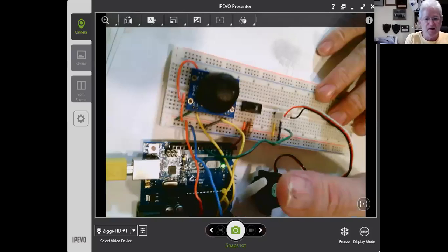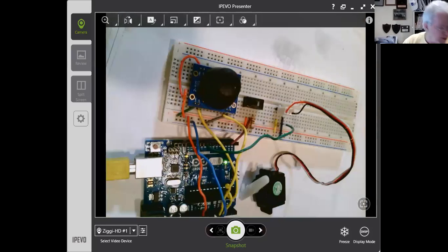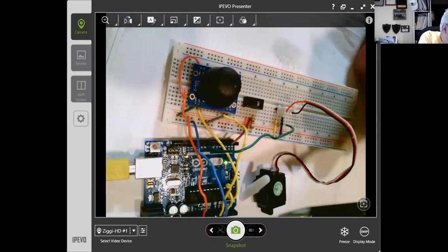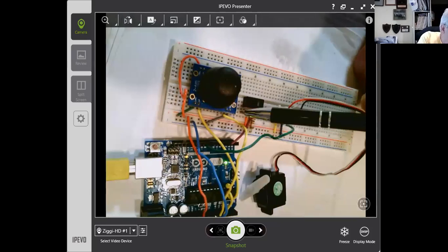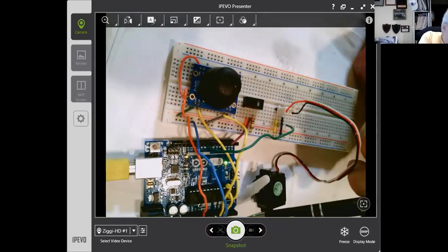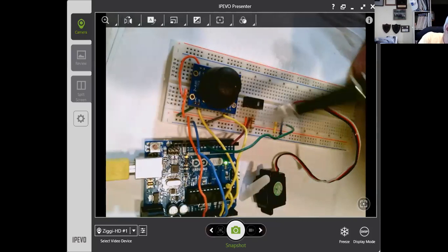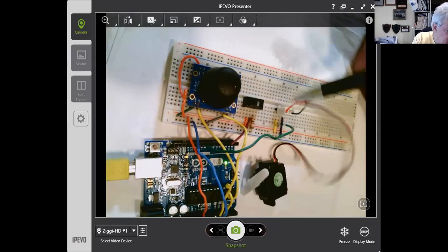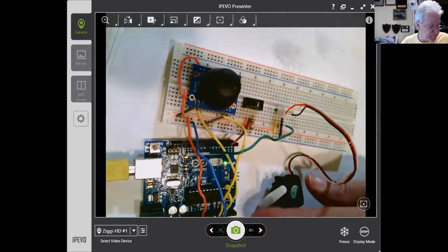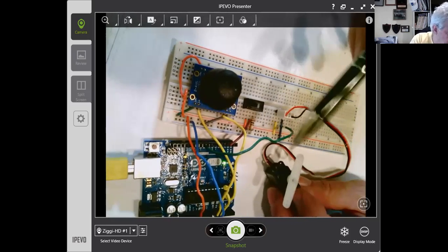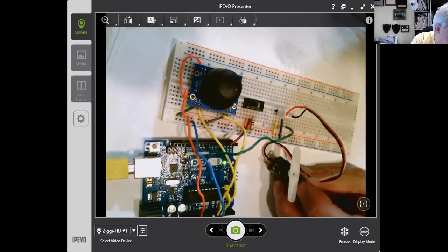So let's share the screen. Let's go to the document camera and let's take a look at what we have. Now, this Arduino board has 2 yellow wires here. One of the yellow wires is all that we need to go to analog pin 0, and that's going to the up-down part of the joystick. The A1 we really don't need, but I just used the board with the joystick from my previous example when I just had the joystick controlling forward, backward, left, right movements and displaying various LEDs. So that's why I have something erroneously not needed connected to A1.